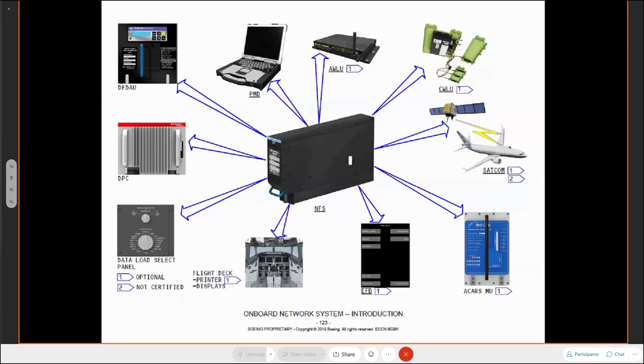It will drag that information from the server, store it on the hard drives, the new LSAP, and then maintenance will come along and copy that LSAP to a destination. So an example that I always use is something like the flight management. The FMC, the flight management computer, every 28 days you have your nav database update.